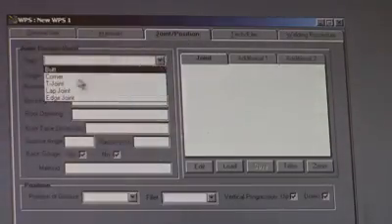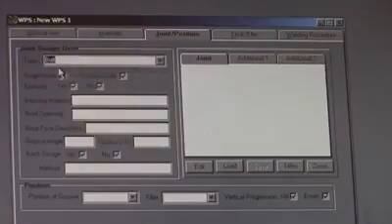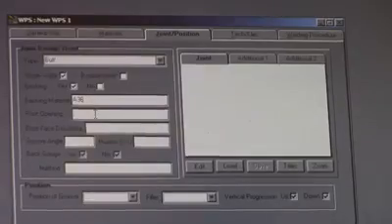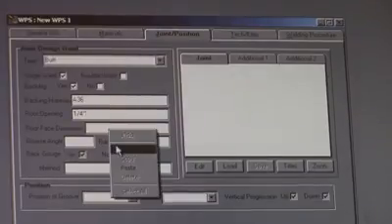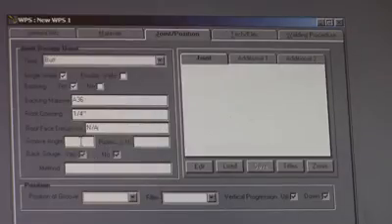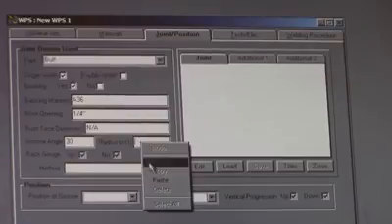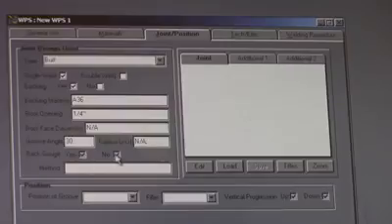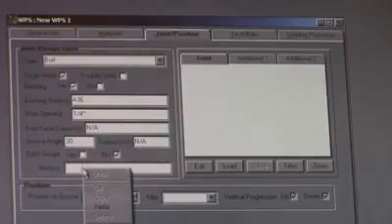Joint or position. Joint design used. We're going to do a butt joint. We're going to do a single weld. We're going to make it easy on them and put backing in there. Backing material is going to be the same as the rest of it, A36, with a root opening of 1/4 of an inch. Root face dimension, we're going to keep it a point, so I'm just going to put non-applicable. Groove angle, we'll go 30 degrees. Radius, non-applicable. We're not going to back gouge, so there is no method.